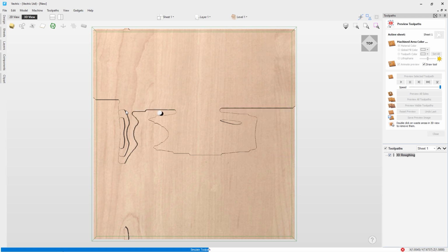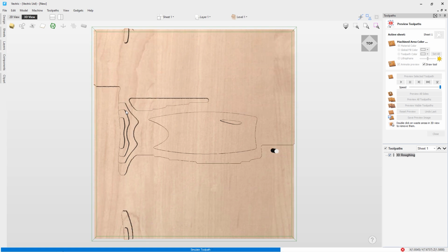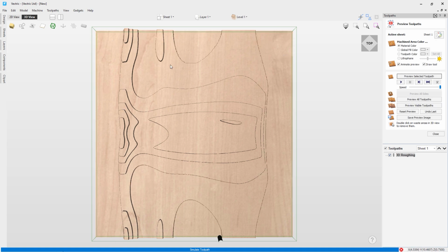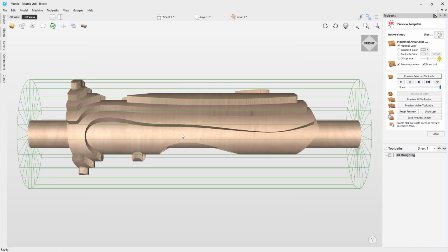So it's first machining it or creating it as a 3-axis job, and then wrapping it around the axis that is specified in our job setup form, which for us was the y-axis being wrapped to A. So in a moment here, when this is all finished, this axis will be wrapped, and we'll see what it looks like as a wrapped roughing pass.